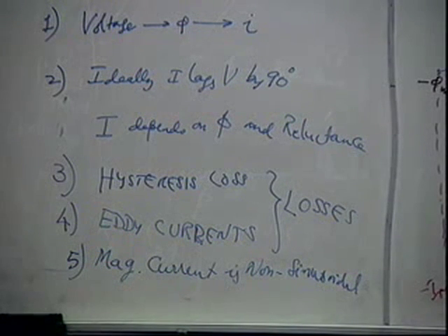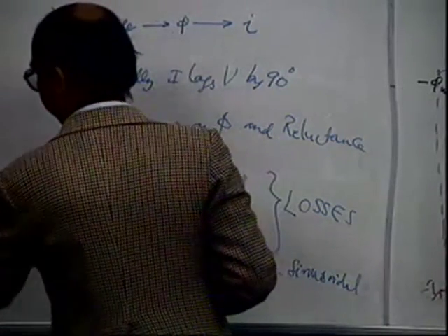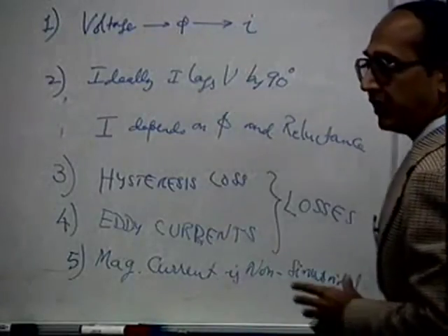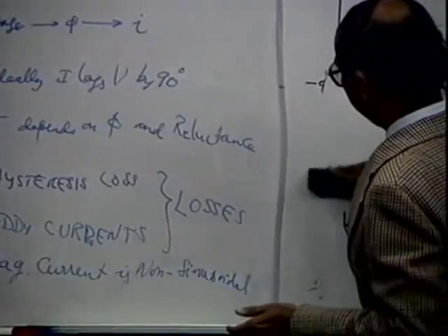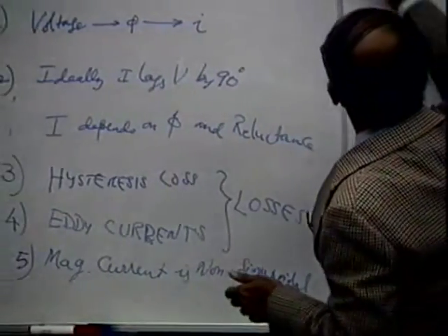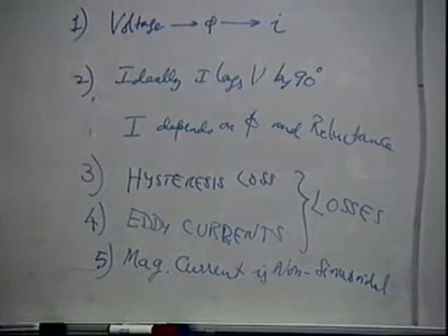So these are a few of the phenomena that you observe. In a DC case, if I plot the various values of phi with respect to I, would I get a straight line? In the case of a DC circuit, phi versus I depends upon the material. It will be slightly in the linear region and become saturated later.